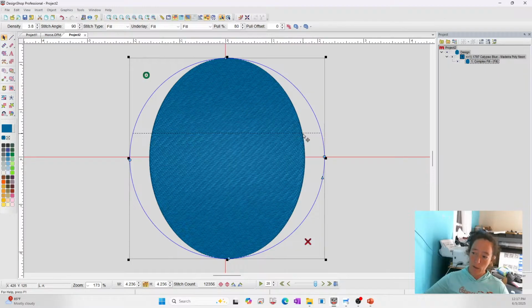As it goes across this way, the needle makes a needle penetration. Let's say here, it goes down into the bobbin, grabs the bobbin thread. It comes back up. Now the top thread is connected to the bobbin, and it moves over at high speed. So that thread is going through a hole, and it's being pulled in this direction, right? So that hole is trying to shift this way. Every time it's sewing this way, all those holes are trying to move in the direction that it's sewing, so that whole edge is shifting in, right?